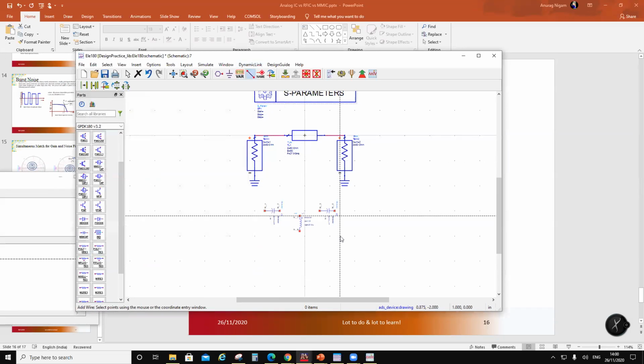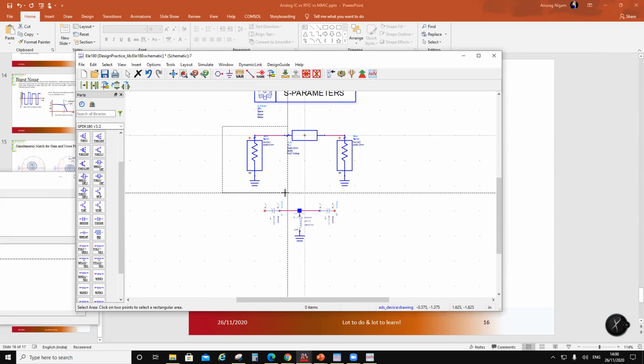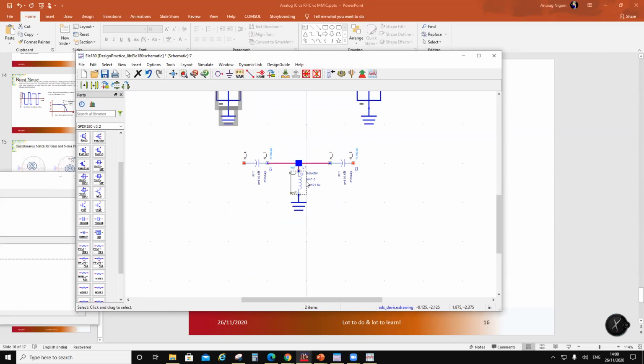Okay. And I will bring a ground plane out. So basically I will connect a ground here for now. Okay. And of course you have to take care of the ground inductance. But what will happen is that the ground inductance is common throughout. So really I will put a pin here and forget about the ground inductance. I mentioned to you that the ground comes with the inductance because of the bond wire. So when I put a pin in here, it won't really matter. Because everything will be referenced to this ground, which is an inductive ground, I don't have to compensate over here.